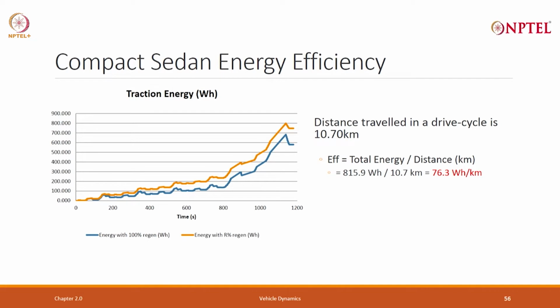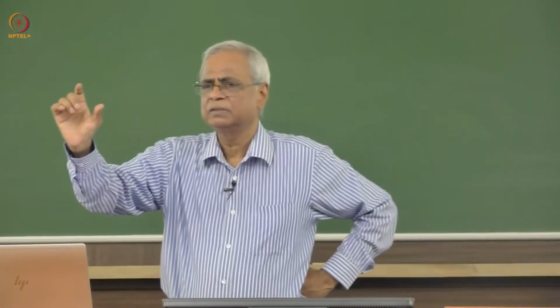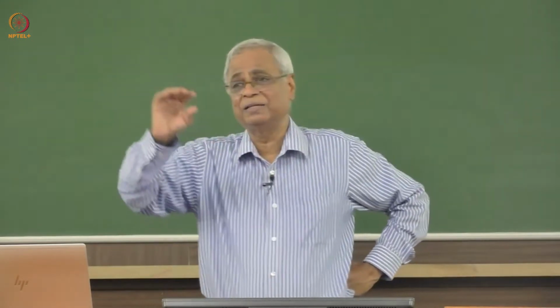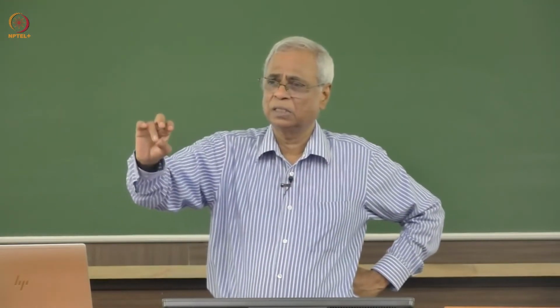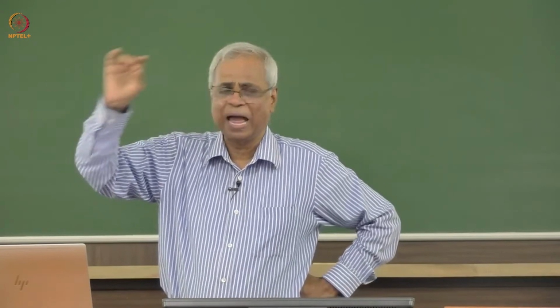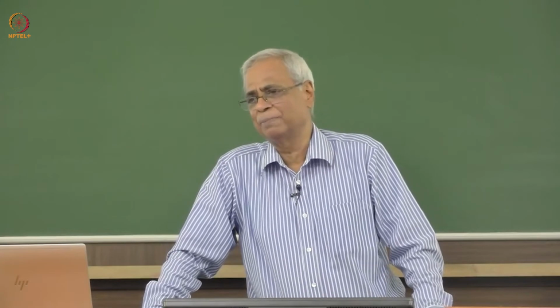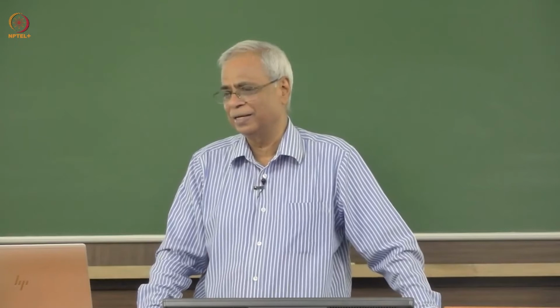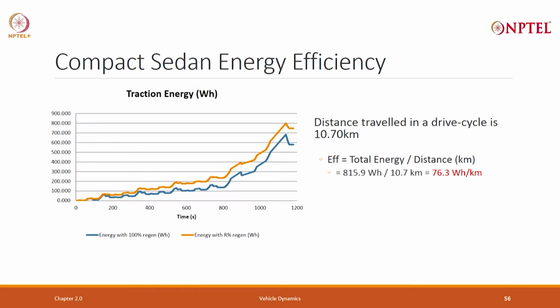First I put the velocity numbers versus every second in the spreadsheet, find the distance travelled, convert it into meters per second, and find the acceleration. Then I find all three forces: the acceleration force, the rolling resistance force and the aerodynamic force. I find the total force required. From there I compute torque on the one hand and power on the other, integrate it to get the energy, and integrate the incremental distance to get the total distance.